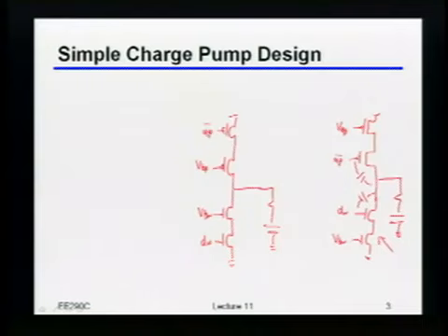Because I put ground on that cap, which is kind of implying that I want everything to be relative to ground, right? Okay, so if I want everything relative to ground, out of either the PMOS device or the NMOS device, when it's off, which one is connected to VDD? At its gate. Up bar. Yeah, up bar, right? So the PMOS device, when it's off, will be VDD at that gate.